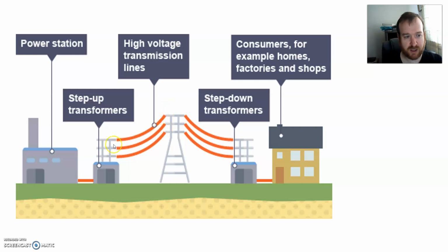That's not what's happening. The total energy going into a transformer is almost identical, they're really efficient, to the total energy coming out. So the total energy in the high transmission is going to be really similar to the energy coming out of the power station. You lose a little bit through heat in that transformer, but for the most part we can actually assume that it's identical, because step-up transformers are very close to being perfectly efficient, especially the big ones that the national grid uses. So something else must be happening, because if I'm increasing the voltage, something else has to change, and that's the current.